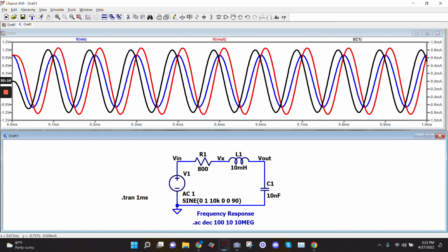Well, the thing is, if you were to plug this in on an oscilloscope and do it in the lab, you would see this. If you put an AC signal into an RC circuit, you're going to get a 90-degree phase shift that you can actually physically see on the oscilloscope. And a 90-degree phase shift would be a quarter of the cycle time delay, whatever the cycle time is, or the period. Cycle time and period are used interchangeably. Whatever a quarter of that is, that will be your phase shift.